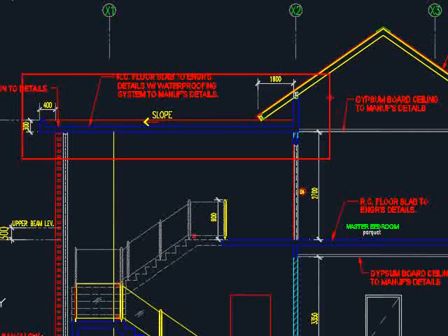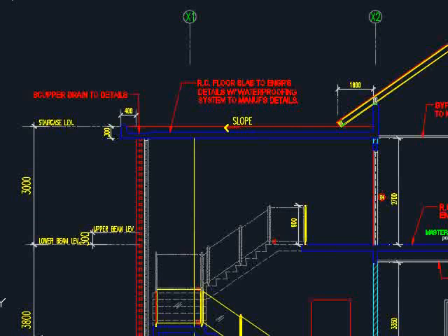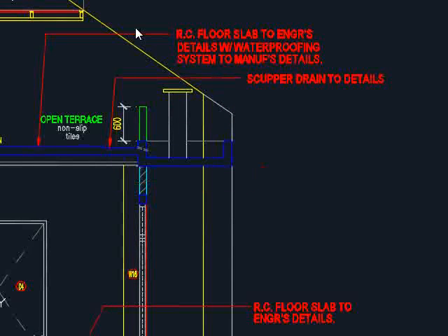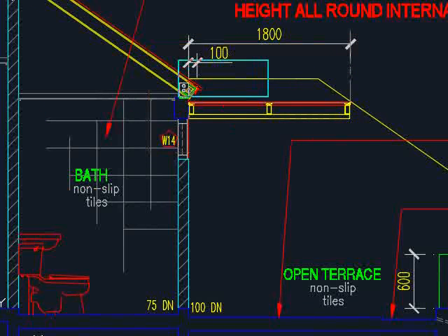Also mind the special design here, which you need to compare with the floor plan in order to observe what this actually is. Most likely there is a flat slab with a certain degree of gradient so that the water can flow from the roof onto the slab, and then to the gutter. There is another special feature here. You will need to pay extra attention. Again, you will need to refer to the building in various aspects, most likely looking at the view as well as the plan, in order to figure out what these are. The same goes for this part. You might need to study and imagine what these are. Most likely this is a roof extended from the wall, which is not an RC roof.